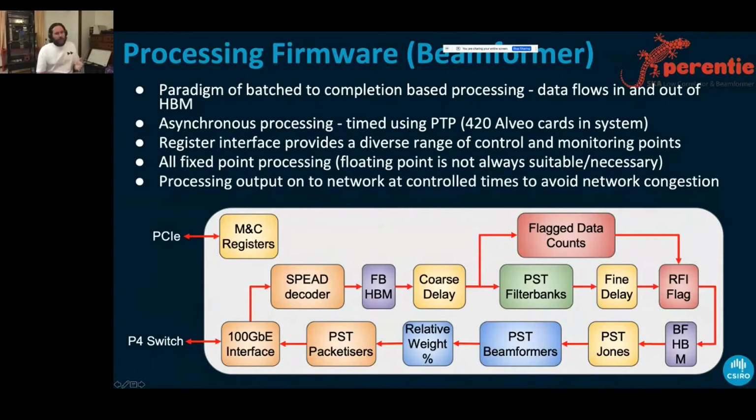And then from this stage, the beamforming can be performed. It's a summation, where various per-station and per-beam complex weights are applied. And there will be some correction for the ionosphere, etc. Then we will have formed multiple beams, and if I remember correctly, up to 16 beams to point at different directions in the sky. And then we can send this information to another processor in the telescope. So that's what we do in the beamformers.